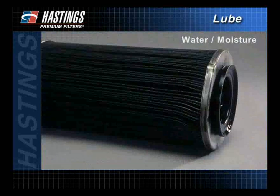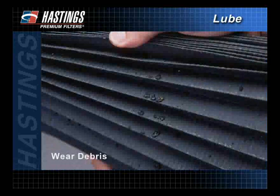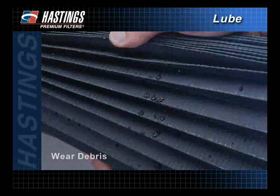Certain oil additives will trap water and cause a gel-like coating on the filter media. It may appear clean, but when tested, will show a restriction if moisture is still present. Any wear debris on the media is a sign of trouble.